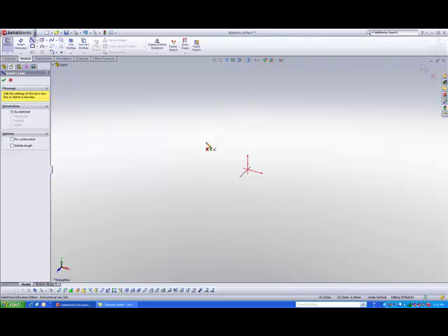And we can change the different planes that we are sketching on simply by pressing the tab key that you find on the keyboard. So once again, to change the planes that you're sketching on, just press the tab key a couple of times and see it toggle between the different planes. Another way to help with visualization is this red color origin that you see in the center of the screen. As I press the tab button, you'll notice the orientation of the origin will change accordingly.